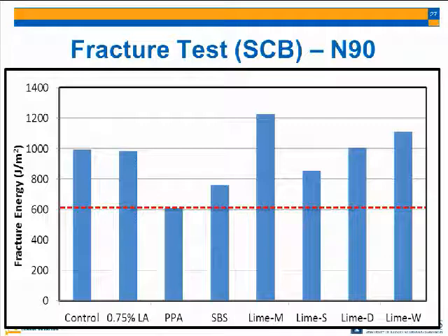Nobody measures the permeability. You said the unrelated mechanism of getting in is suction or diffusion, and permeability. Obviously you can still have water in the aggregate, but why don't you measure permeability? Because that tells you about the connectivity of the pores. I think we should. Yes, that's a very important thing that we need to measure for any asphalt pavement that we are going to lay in the field.